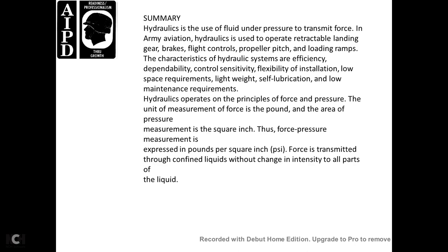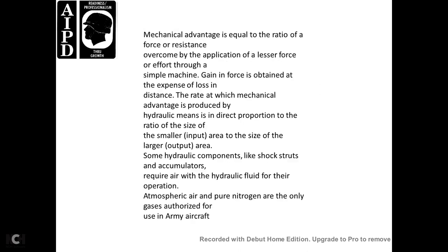Hydraulics operate on the principle of force and pressure. The unit of measurement of force is pounds, and pressure is force per unit area, expressed in pounds per square inch, or psi. Force is transmitted through confined liquids without changing intensity to all the parts of the liquid.